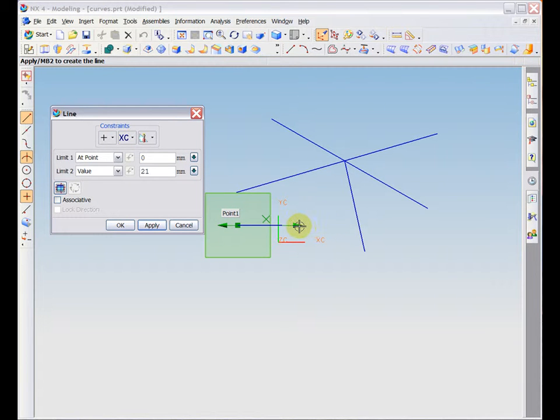The third button at the top of the dialog box controls the plane in which the line will be drawn. Note the shaded plane representation shown when one of the principal coordinate planes, for example the XZ or the YZ plane, is selected. Also note that this option can be difficult to use unless our viewing plane is oriented in the same direction as this drawing plane.